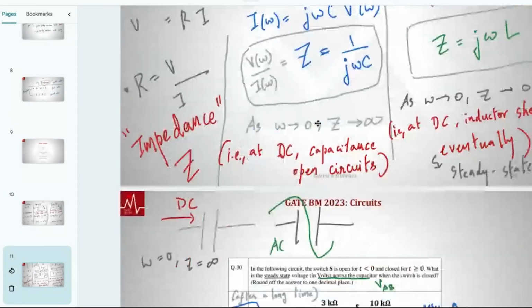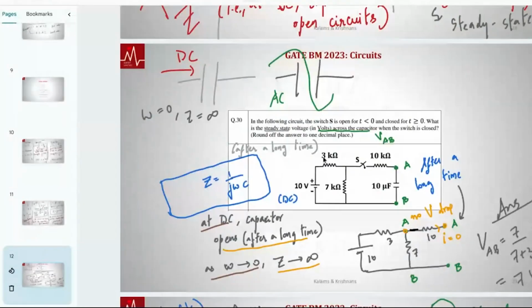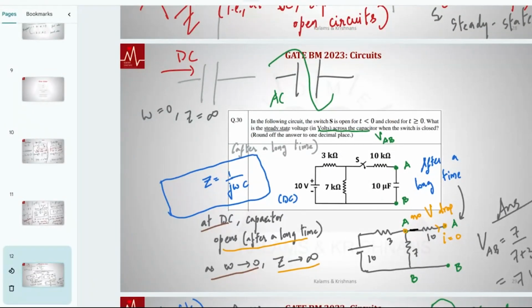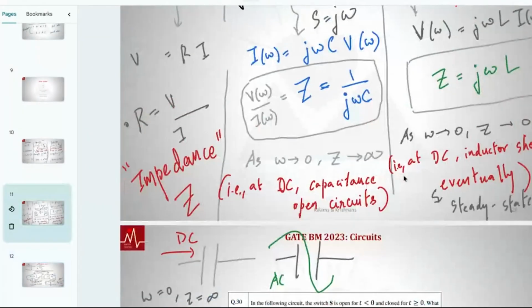So based on this, we solved this capacitor question. We got to a stage where we can comfortably solve purely resistive circuits. They give an RC circuit like this. Many of the questions essentially boil down to a purely resistive circuit. Given a circuit with a capacitor, but under steady state condition, initially this, that, and all that, typically it becomes a simple resistor circuit. The capacitor opens, the inductor closes, and all that. So we have discussed that. That is where we stand.